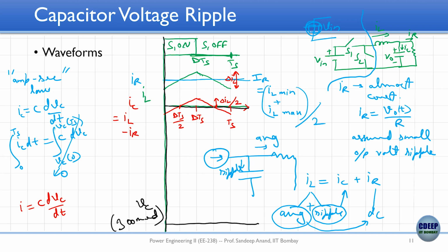Similarly, this other point I can write as (d plus 1) times Ts by 2. So I am just assigning appropriate timing instants to all these 4 instances, right. Is that okay? The midpoint is dTs, of course, and the midpoint between 0 and dTs is dTs by 2, which is where the current is crossing 0, and then again the current is crossing 0 at (1 plus d) times Ts by 2.